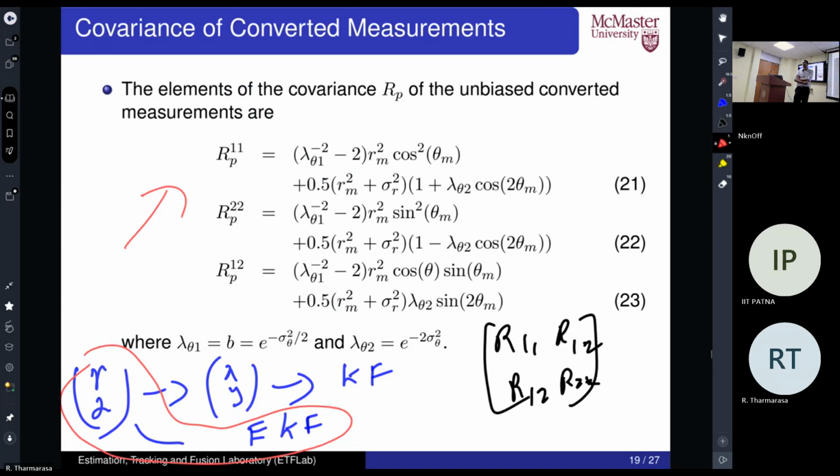So start with some model and do the tracking, and if the performance is not satisfactory, first think about the CRLB. If you have enough room to improve, then think about machine learning or whatever alternative. But if you already reach optimal or close to optimal, either you have to replace a sensor or add more sensors.